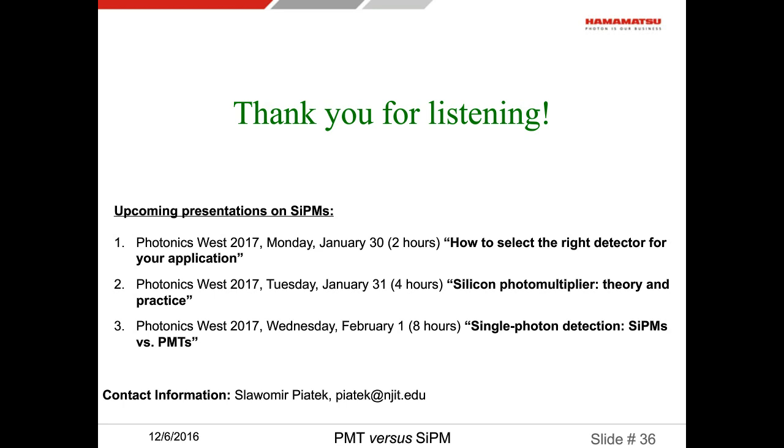Yes, for SiPMs, that is correct. The reason for that is that breakdown voltage is a very sensitive function of temperature. So if I keep bias voltage fixed and temperature changes, the breakdown voltage changes, and that changes overvoltage, leading to either higher or lower gain, depending on which direction the temperature has changed. And so in temperature changing environments, it's highly advisable that there is a feedback circuit that will stabilize overvoltage against temperature changes.